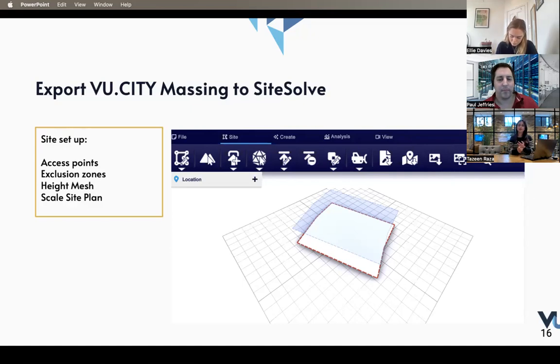Secondly, you can see exclusion zones. Maybe there are some areas that we don't want the algorithm to generate any building on. Maybe that's a landscaped area, a historical landmark, or a potential car parking spot, anything of the like. Often for master plans, there might be different site edge setbacks for every single plot. Maybe within a plot, you are not allowed to build, let's say, 10 meters from the edge, and for others, it might be 4 meters. So you can start drawing in and customizing that to your site.